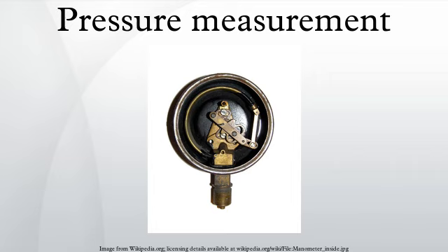Simple hydrostatic gauges can measure pressures ranging from a few torr to a few atmospheres. A single-limb liquid column manometer has a larger reservoir instead of one side of the U-tube and has a scale beside the narrower column. The column may be inclined to further amplify the liquid movement. Based on the use and structure, the following types of manometers are used: simple manometer, micromanometer, differential manometer, inverted differential manometer.